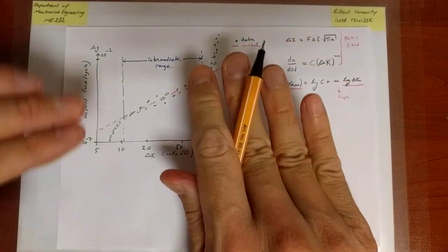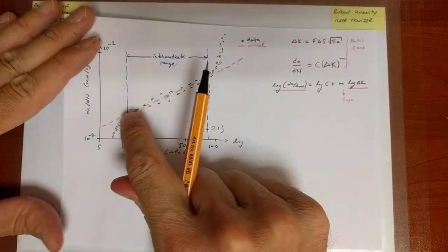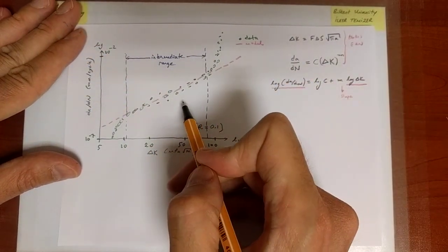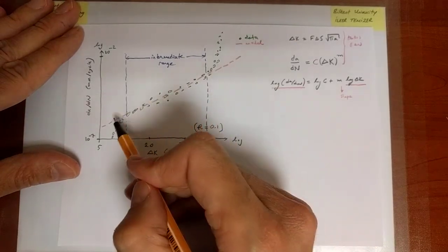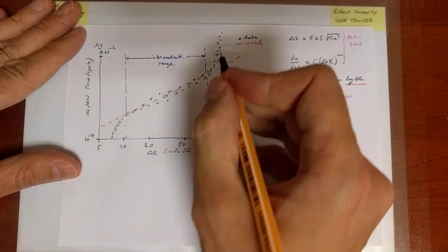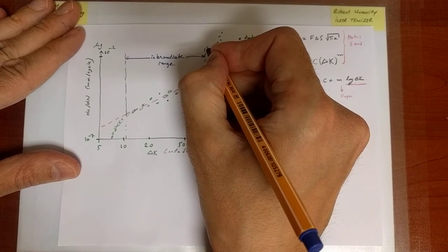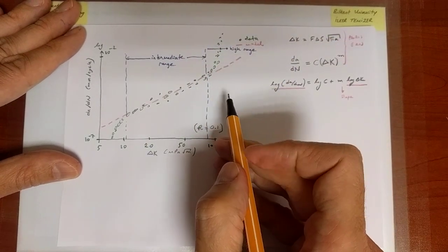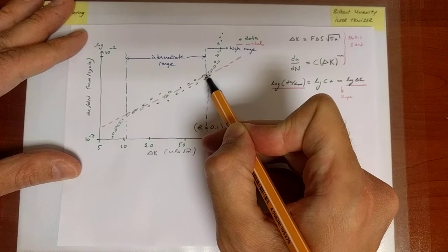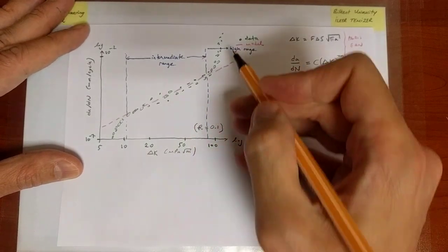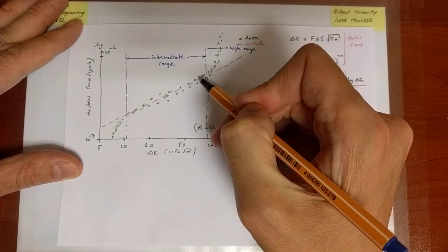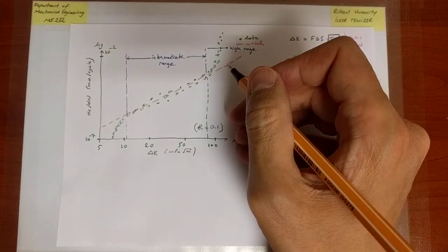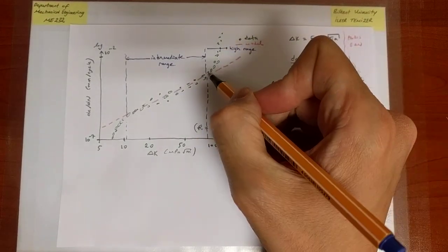In fact, that is the motivation for the Paris equation. You first do the experiment, you see that there is an intermediate range where the data in the log-log plot falls almost on a line, and that motivates you to write or propose the Paris equation. But now there are two other regions. First of all, there is the high range. Now, the high range is where the crack growth rate deviates from being linear in the log-log scale, linear with respect to delta K, but it increases much faster than the rate at which delta K changes. So the Paris equation cannot capture that.